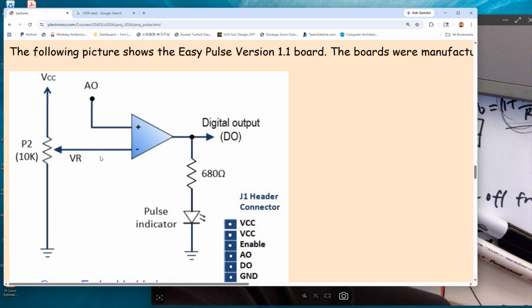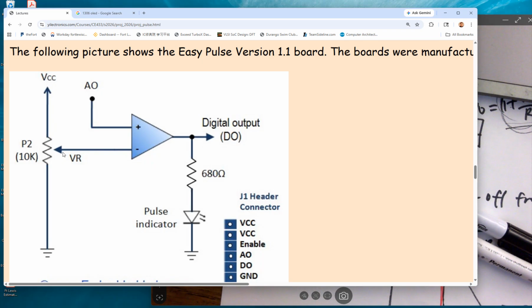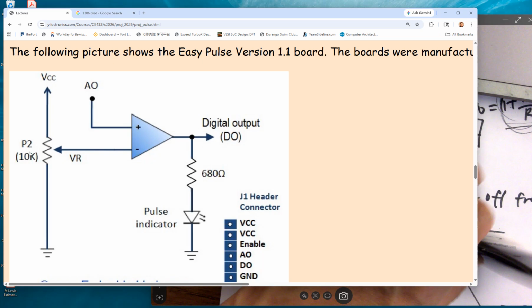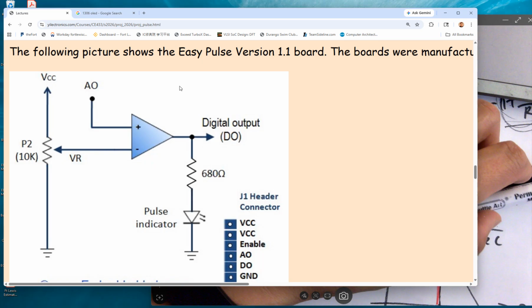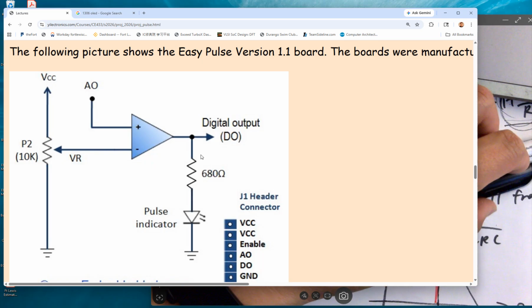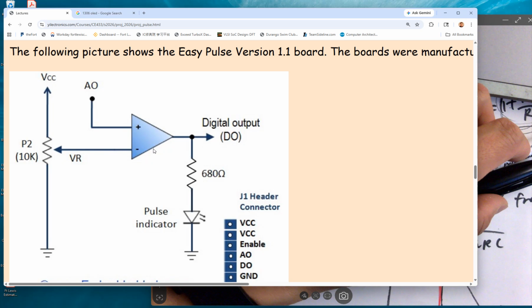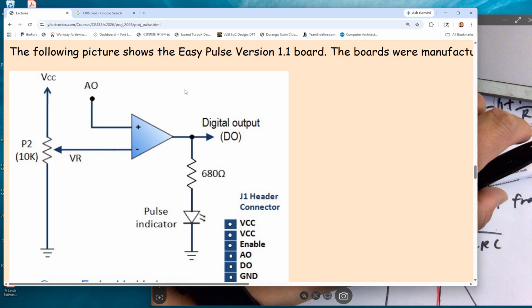And it's comparing to the reference voltage shorted to the inverting terminal. And it's a potentiometer. It can change it to a certain DC level. So whenever it passes that DC level, this one will be switched on, right? So showing the DC voltage. In the other case, it will swing back to ground, because all these ones have 0 to VCC power rails. So this one will swing between 0 and 1, performing like a comparator's digital signal, and that will turn on and off this LED.